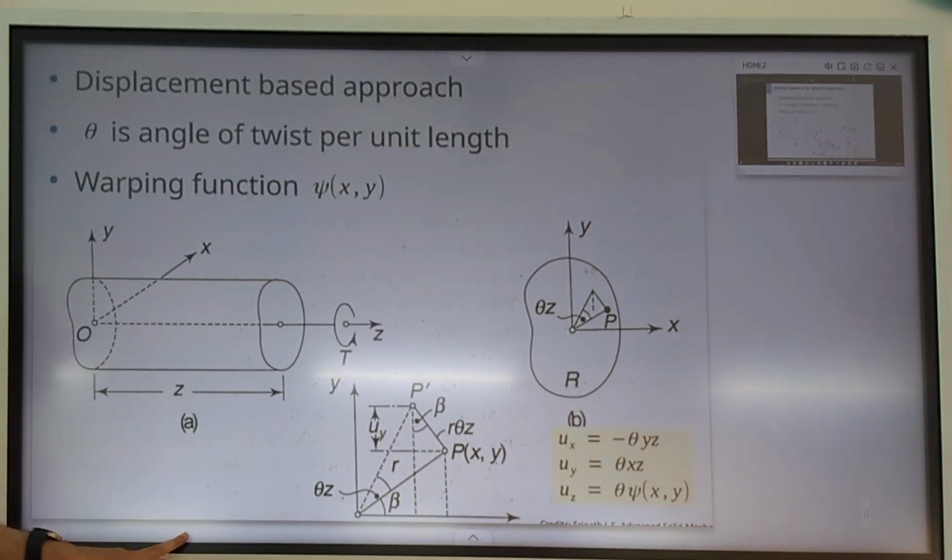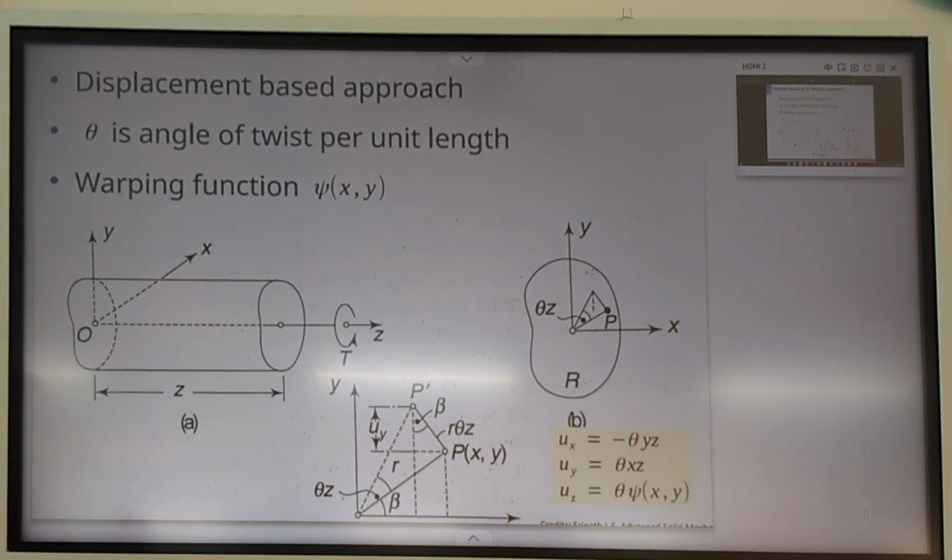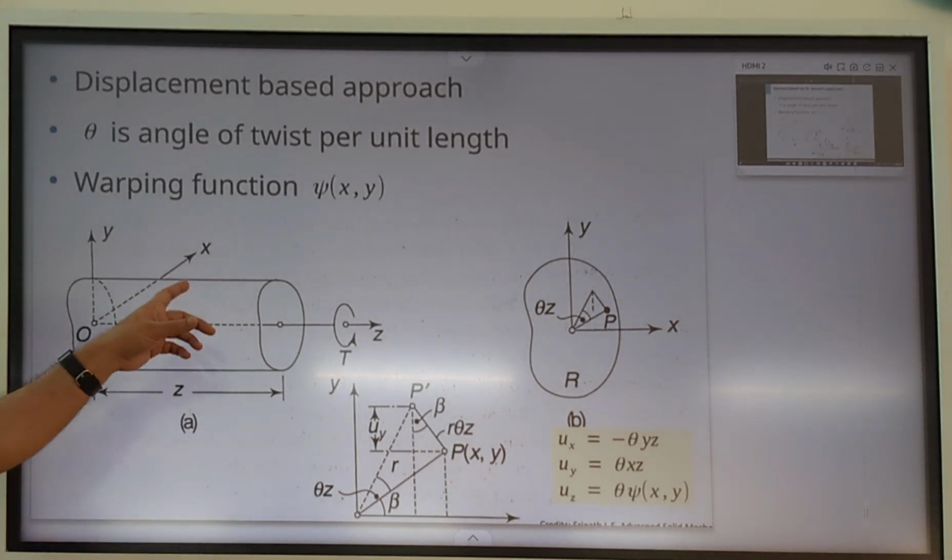What we are interested in, in non-circular shaft design or analysis, is that when such a non-circular shaft is twisted, subjected to some external torque, we want to calculate the maximum shear stress that is getting induced. To check how to design it, we will limit that maximum stress within the allowable material stress. And second, how much it is deforming. For some applications, such as in machine tools, we want the spindle or tool holder to be very rigid, so we want to control the deformation. So we would also like to know what deformation is being produced when we are twisting a non-circular shaft.